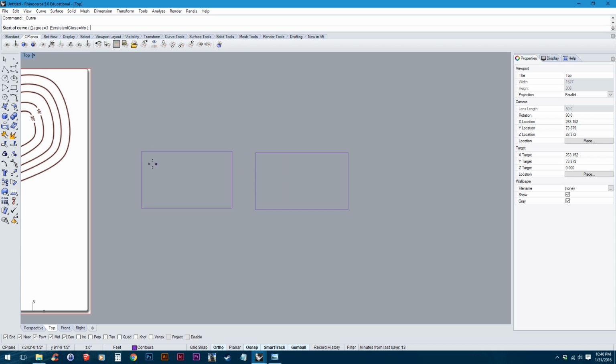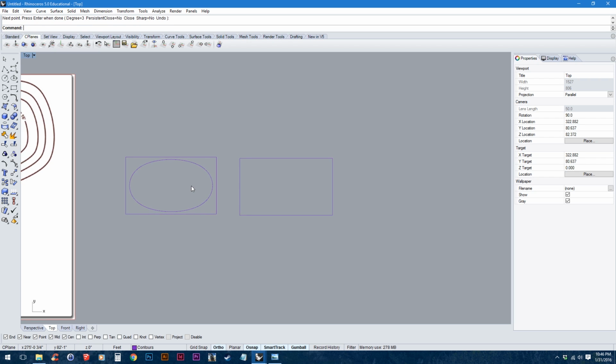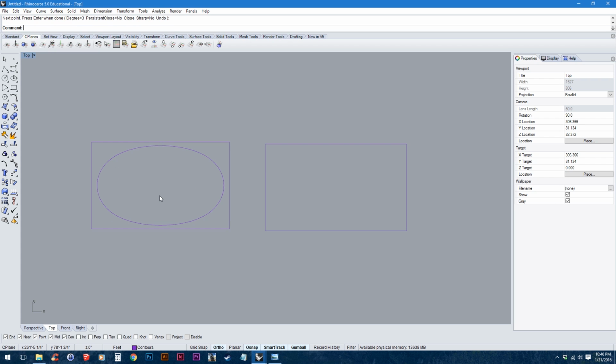So with the first tool here, this one will draw the polyline kind of on the inside of those points that you just selected. But with the interpolate points one, this will draw it basically on those points. So it's kind of up to you which polyline tool you want to use. You'll have to experiment with both to kind of get the feel of each one.